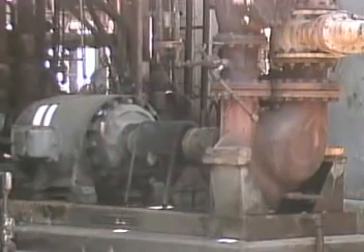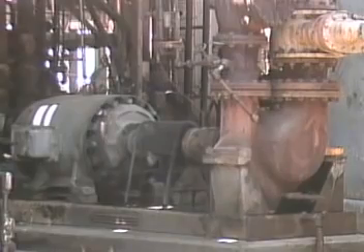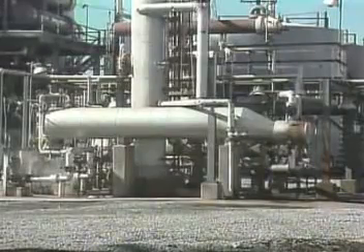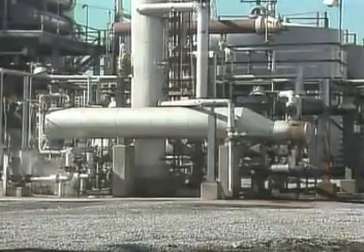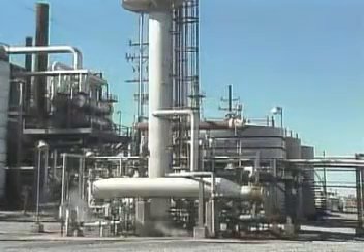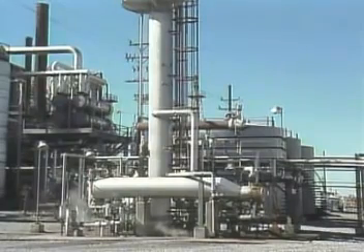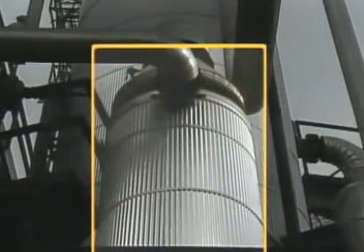As we've seen, a forced circulation reboiler system requires a pump to move liquid. Reboiler systems that do not use pumps to move liquid from the tower are called natural circulation systems. In these systems, liquid circulates naturally as a result of the difference in density between the liquid in the tower and the liquid in the reboiler. One type of reboiler that's used in natural circulation systems is a thermosiphon. A thermosiphon is basically a shell and tube heat exchanger.